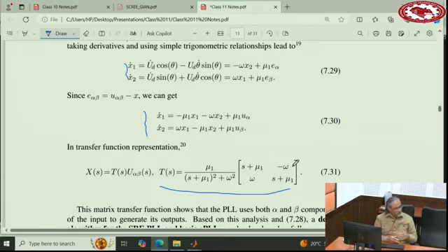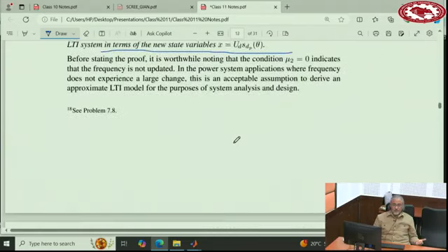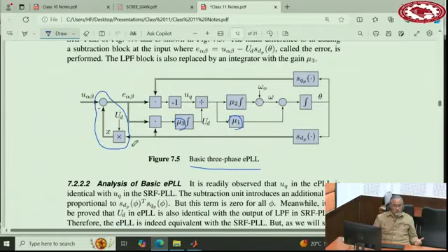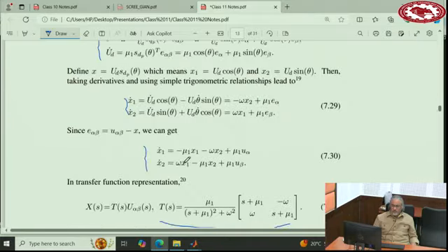Always people in engineering, when there is a nonlinear equation, they want to derive a transfer function, they linearize it. They find an equilibrium point, operating point, small signal analysis. But we did not do that. We just manipulated the equations, added things, put some conditions on the parameters, and then we said in large signal, this system is linear. Not in a small signal. In large signal, this system is linear with these transfer functions.